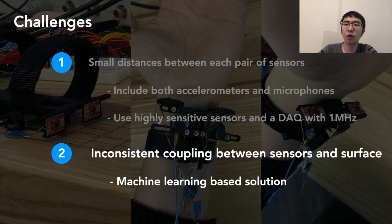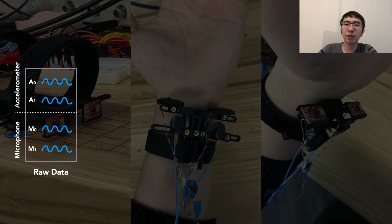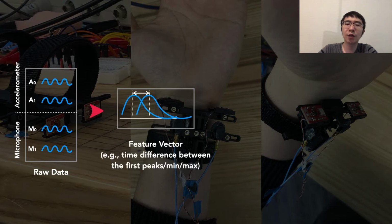To allow for more tolerance, we choose to use a machine learning regression model to estimate the tap's 2D coordinates. To be specific, first of all, the raw sensing data from 2 accelerometers and 2 microphones are collected and sliced using a 0.1 second sliding window. Then, within the sliding window, we use 4 different methods to estimate the time differences of arrival between each pair of the sensors. For example, we calculate the time differences between the first peaks, or minimum peaks, or maximum peaks. In total, we have 24 features.